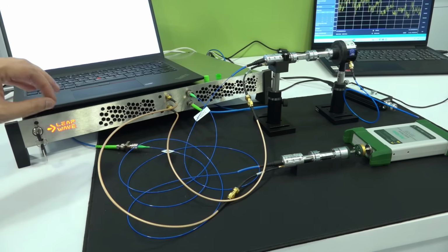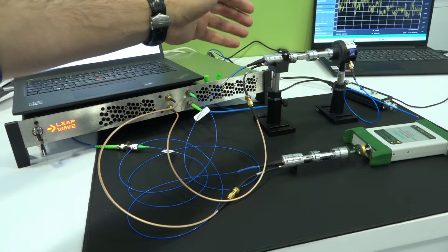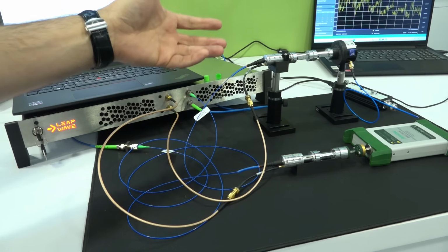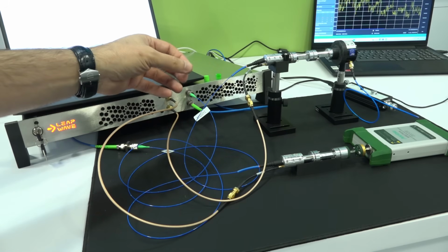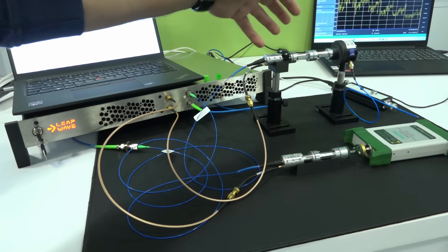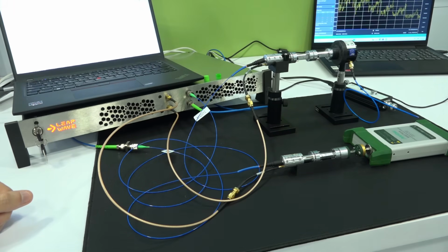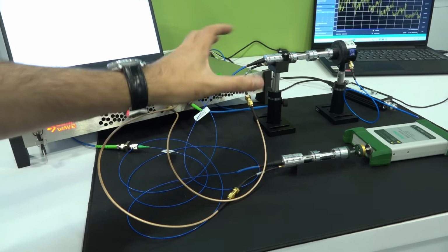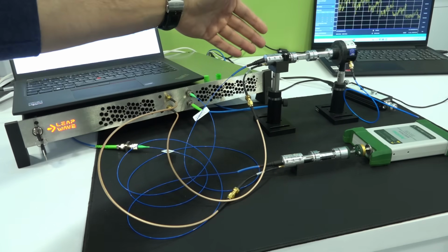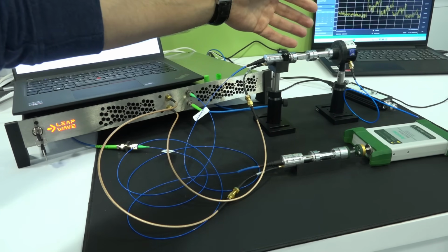So here, what they have developed is that currently they're using 2 DFB lasers, and they are shining them onto the same photodetector, which mixes them together and generates a signal. That's a well-known phenomenon. But then that signal coming in has a huge frequency range. So they have these unique transitions that they have created, allowing them to work at these ultra high frequencies. They have 2 demos here at the same time. Here, there are 2 wavelengths going in, creating a broadband signal sweep going into a detector here that gives you a power reading, because we can't measure up to 500 gigahertz that easily.